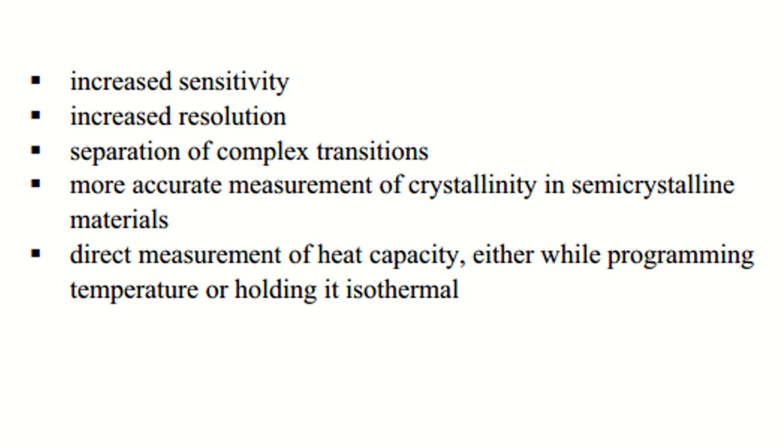First, we need to find the properties of that material over a range of temperature. The temperature range may vary from 100 Kelvin up to its melting point. So we need to find the particular temperature range from which we want to interpret the DSC data. In traditional DSC, it gives only one single signal, which is the sum of all the thermal events.